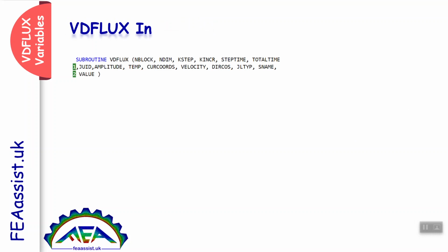VDFLUX variables. VDFLUX has some inputs coming from Abaqus. We need to process them and export the value here as an output to Abaqus.